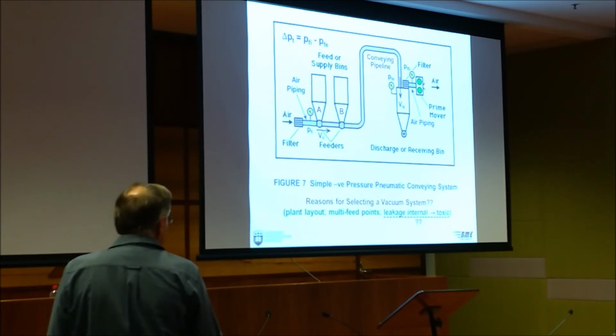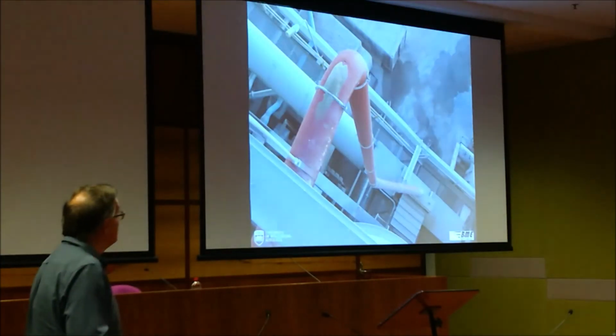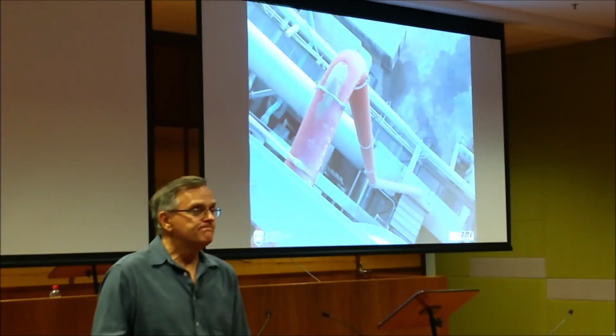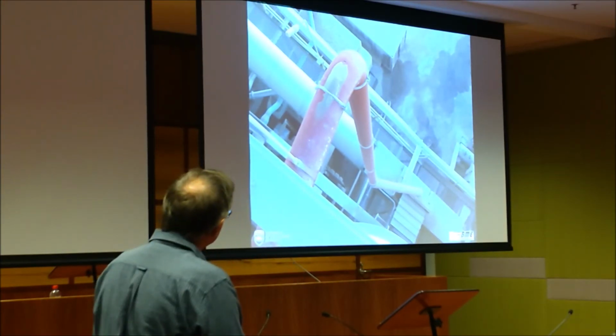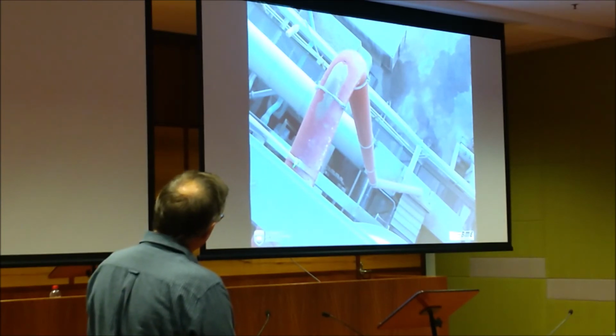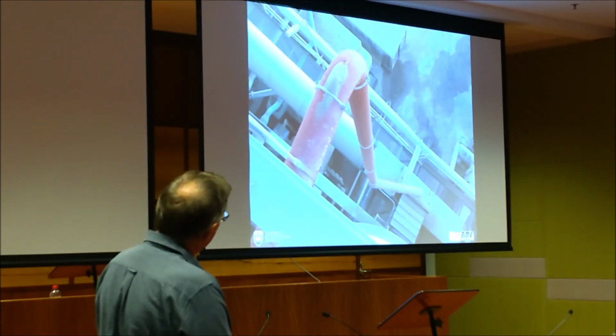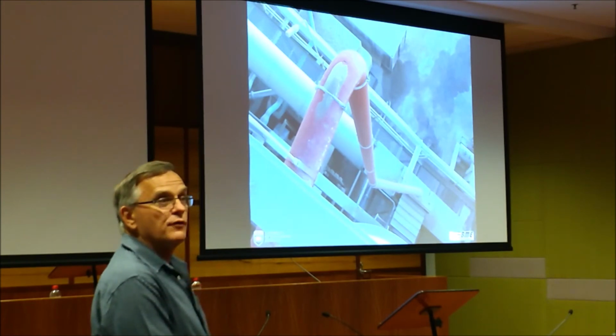Right, so I put a big question mark against that, because here we see a vacuum pipeline, and we see the beginning of a wear hole. Particles are being sucked up through here. Particles impact at that point, and that's where it's going to wear out first.